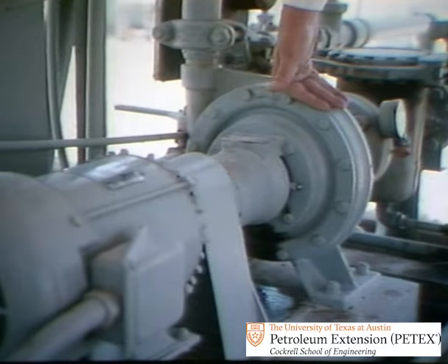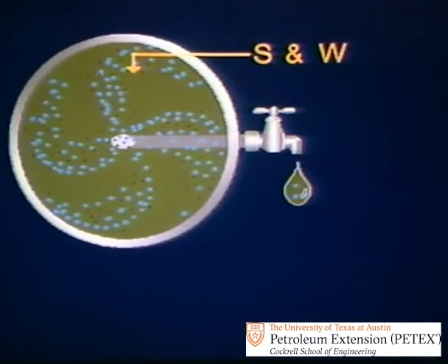But beware. A pump can also cause a centrifuging effect, concentrating dense components, S&W in this case, near the sides of the line. So if you depend on a pump for mixing, verify your sample results.